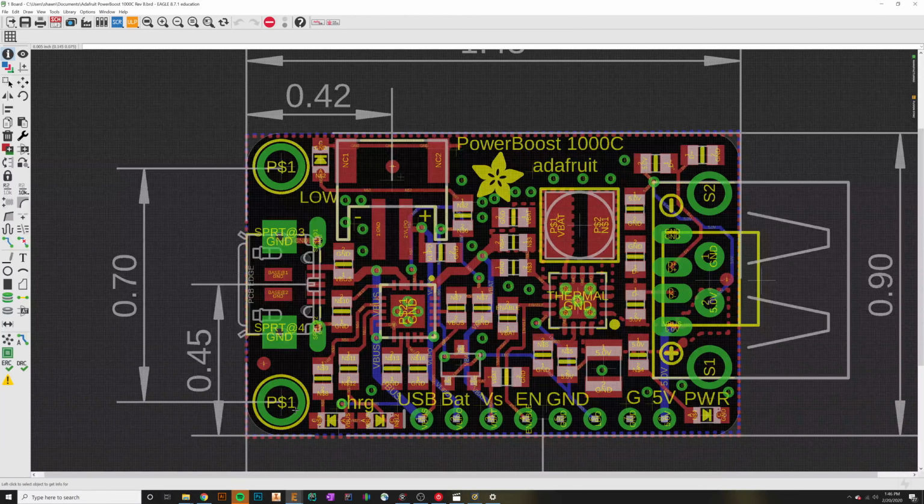Okay, now this is in inches. So just take note that one of them is an X of 0.1 inches and a Y of 0.8 inches, while the other one is 0.1 inches and 0.1 inches. Okay, and once I have that, now I can just go back to my other layout here, and I'm going to go ahead and add a hole. Now the hole by default, the drill size is currently 0.35. I believe that's millimeters. Yeah, it's millimeters in our case. We're going to change that. We're going to save it as millimeters, but instead we're going to make this value 2.5 millimeters. Okay, so that's the diameter of the hole we need.